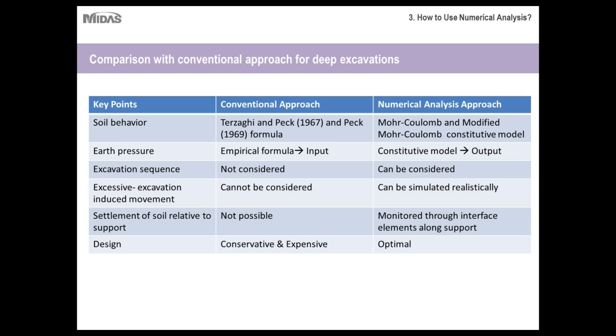And these variations could be monitored easily in your numerical analysis approach, and for that you can apply interface elements along the support height so that you can see the relative settlement that is occurring.